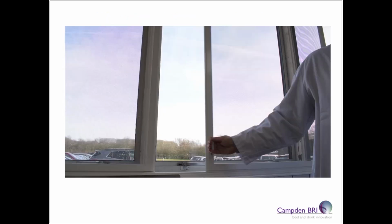Yeah, so with windows, it's very important to avoid windowsills where dust and dirt can gather, and assure accessibility for cleaning. So, for example, if you are to add on a screening window, can you actually get in and around behind to clean it as well? Because that could create extra crevices that become difficult to get behind and clean. And you can see with this example, you've got screening on a window.